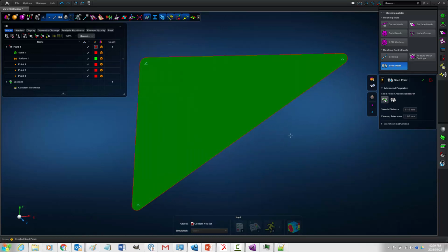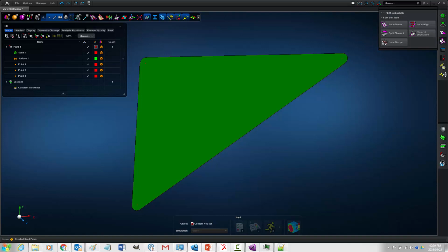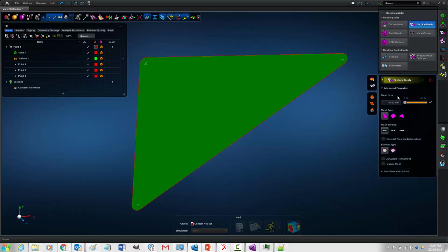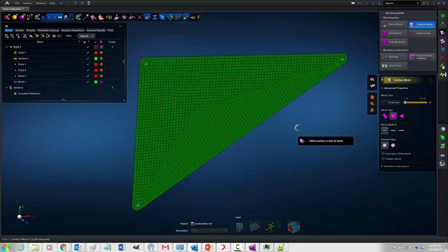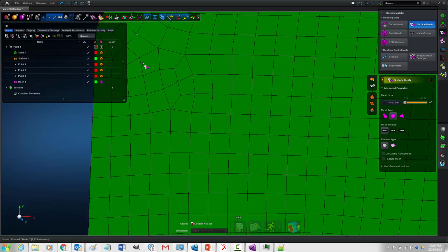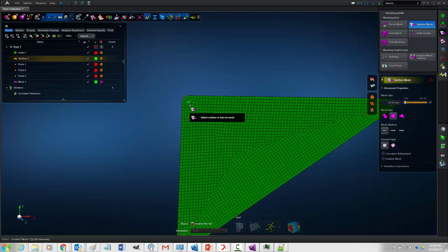So important, I need to get to a stage where I see those three triangles, and those are important because when I'm going to mesh with these elements, and I prefer using quad elements like that, I really want to see that I have an element with a node at that location.